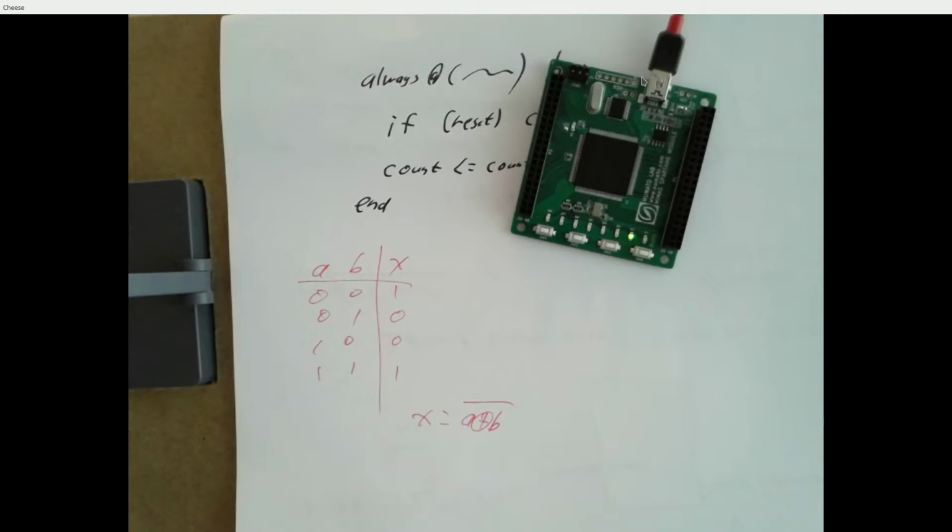So once you get the details ironed out, this is a pretty quick way to develop and work with Verilog. Now we can simulate these designs. We could use the Icarus system, and we could use GTKWave, right? But if you're going to do that, you need to generate the clock yourself.